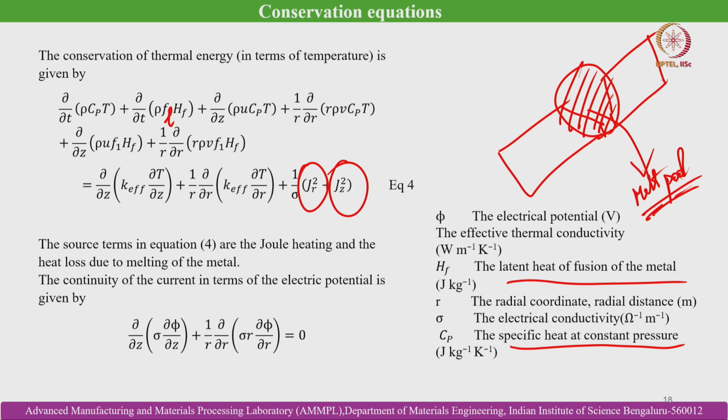Here we have discussed the conservation of energy. Earlier we have discussed the conservation of mass and conservation of momentum. So, these are the governing equations that need to be solved to understand and investigate the transport phenomena present in the melt pool in fusion welding.